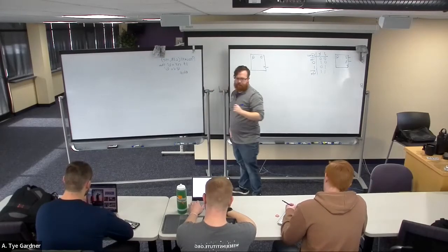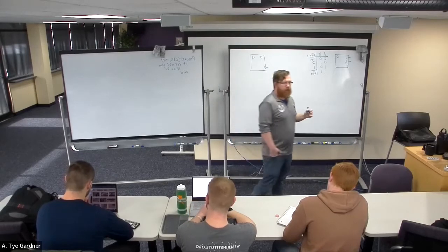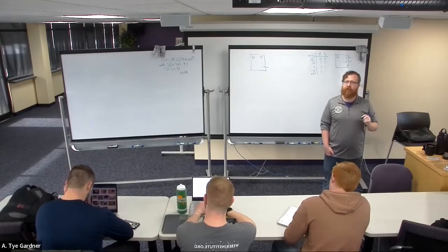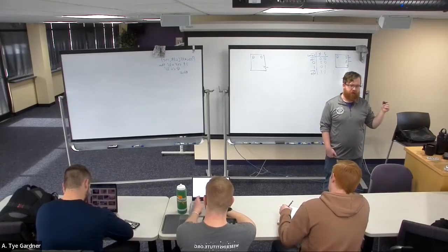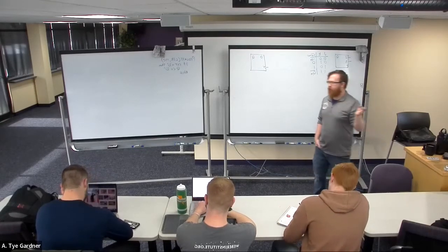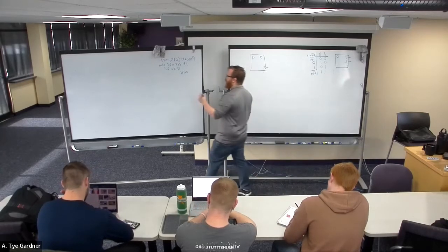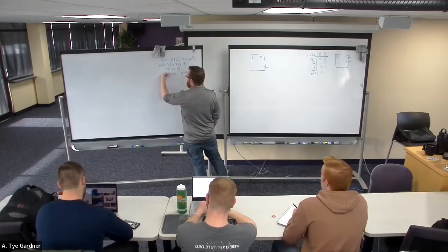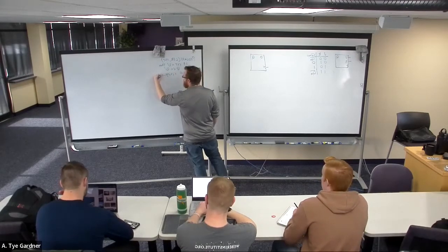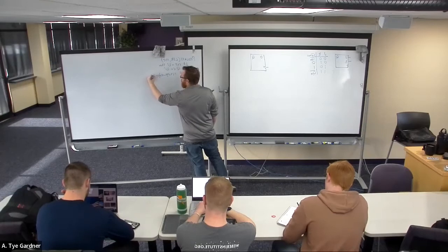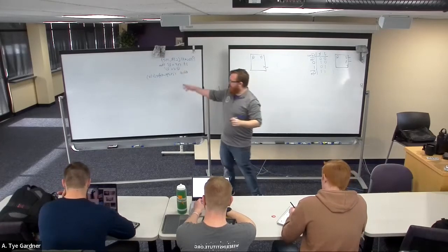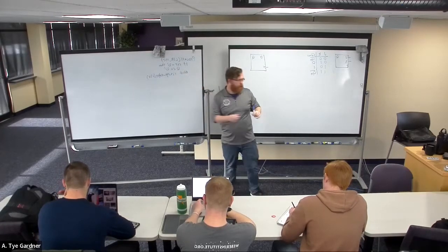Else if. Well, this is the else if that needs to tell it to care about not just when the clock changes, but when it's a rising edge or falling edge. We can do falling edge triggered just as fine. I prefer rising edge. I'm going to most often write RE, but for the sake of review, I'm going to write it correctly, rising edge of CLK, clock. Just so you know, in the future I'm going to write RE as an abbreviation.